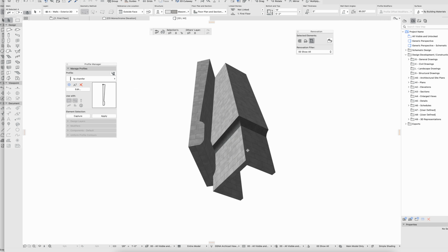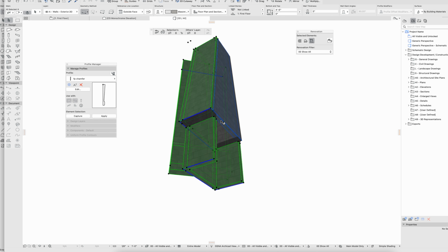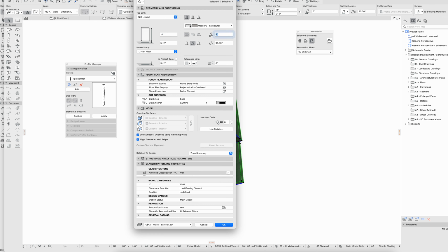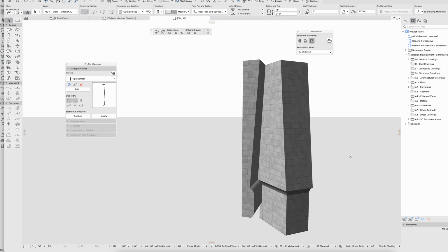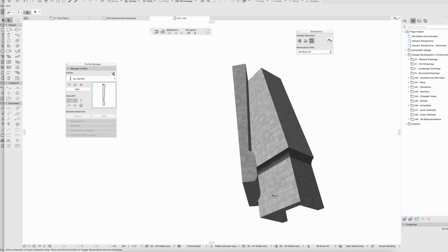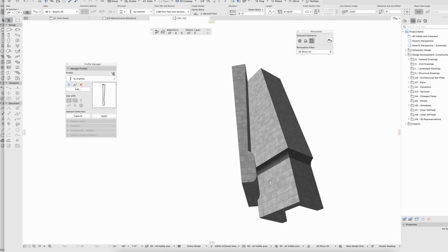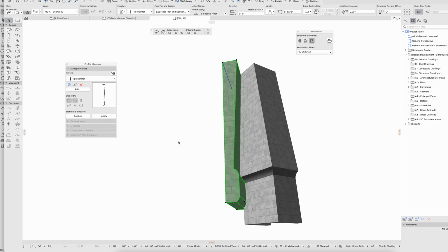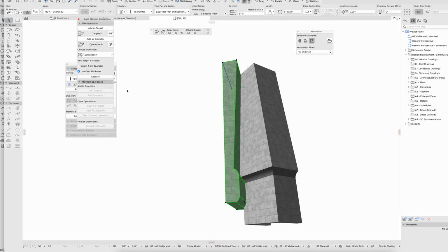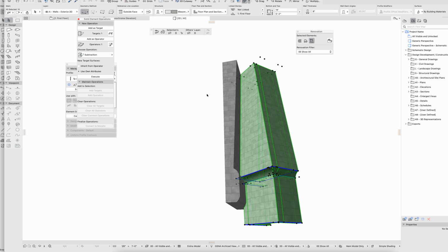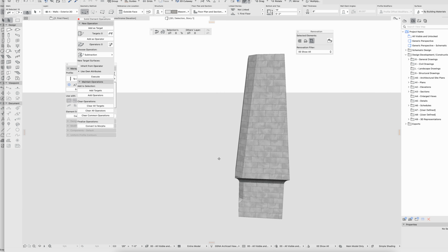And let's go ahead and take these guys and make them just a bit thicker. Like if these walls are 8 inches or something like that, the reference line is all on the outside, so that should be fine. And then where that comes through there, flares in. All right, let's see what this gets us. Operations, that's my operator. Target, subtraction, execute, and what do we got there?